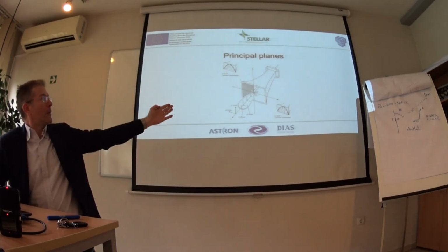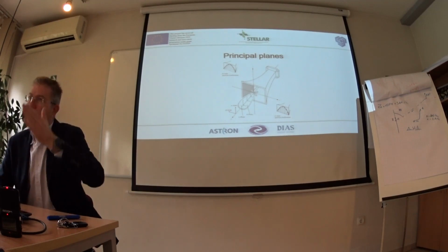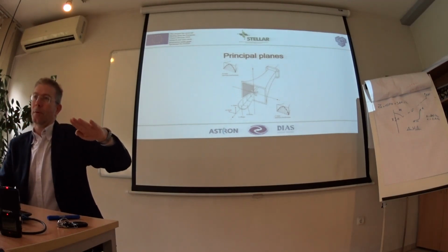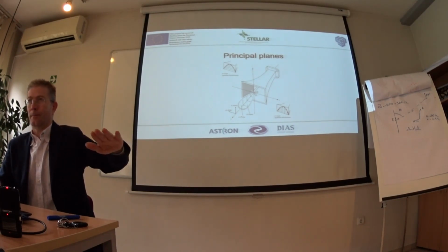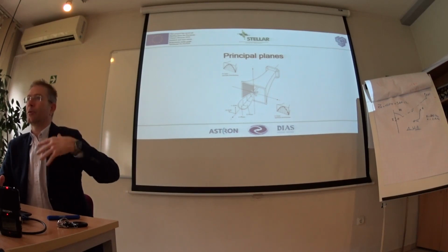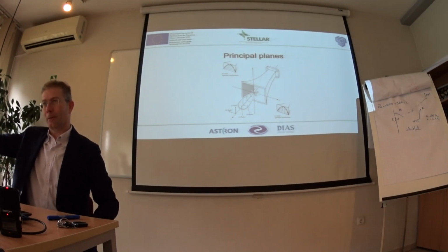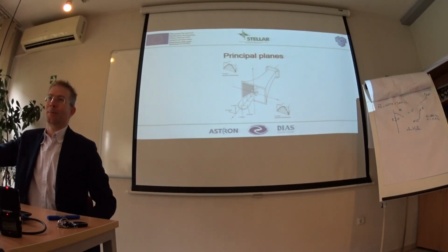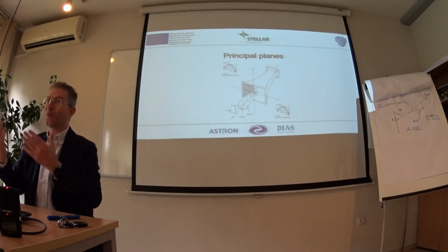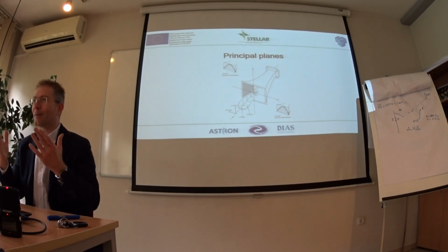And having an antenna, we cut this pattern into sections, cross sections. And the natural way of cutting is horizontal and vertical, which is natural for us. Everything which is at sea level is horizontal, and everything on the orthogonal plane is vertical. The problem happens when we go to space and there is no up and down. But we still have to make a difference in how an antenna radiates.